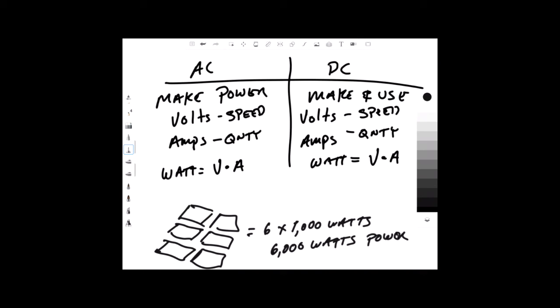So what we need to do is we need to make everybody talk together. Let's say there's a tree hanging over and there's shade here, and these are getting more power. We have to get everybody talking together. So we're going to set the voltage. And the voltage will be, let's just say 36 volts. So everybody has to get stepped up, adjusted up.